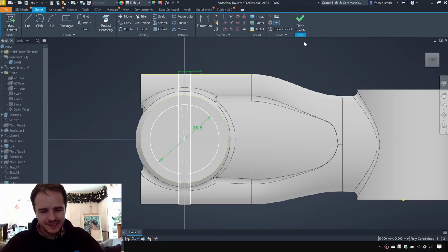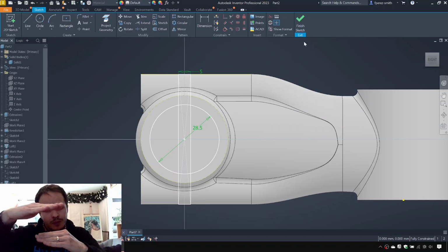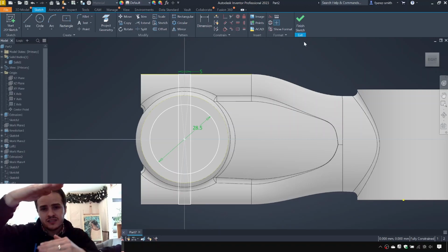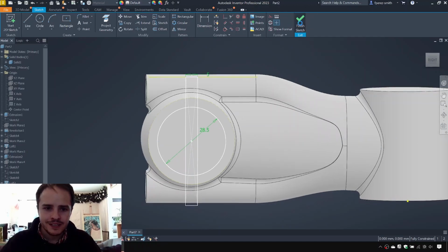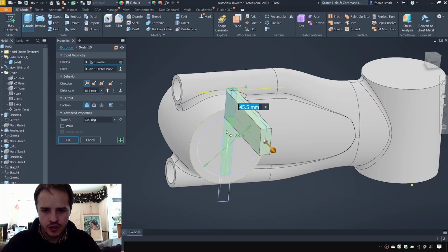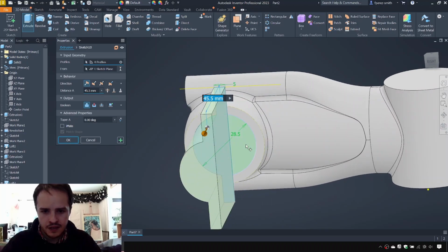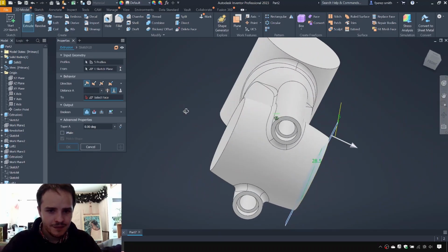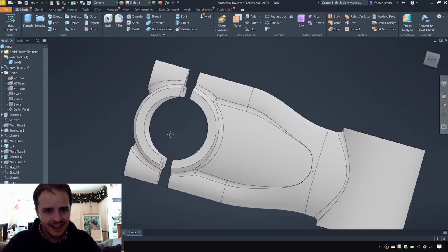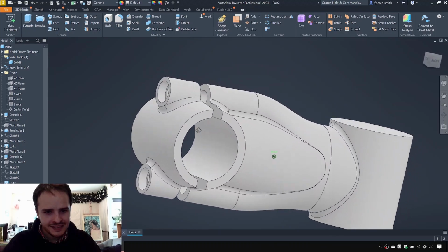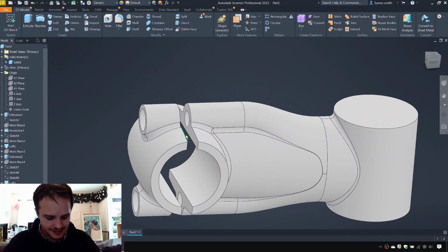You might ask, why do I care about this? Doesn't it matter that it just clears the material? It's if you want to make this parametric and you wanted to change some of the dimensions later on, you want everything to make sense with changes in those dimensions. Cool, so we'll click Finish Sketch. We'll extrude the gap and the hole. Beautiful. Excellent all the way through. And now we have the two sections that make up our part.